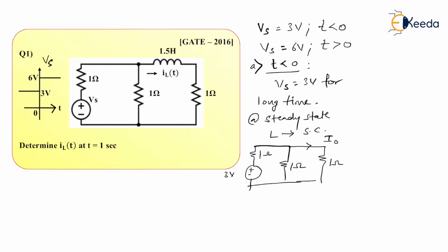Now what I'll do is, suppose if I get a total current, then it will be easy for me. Let's say total current is IT. How to get total current? It's very simple. Total current means the current which is coming through the battery. So total current can be calculated by normal Ohm's law, voltage divided by R equivalent.